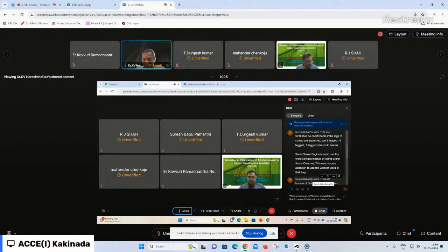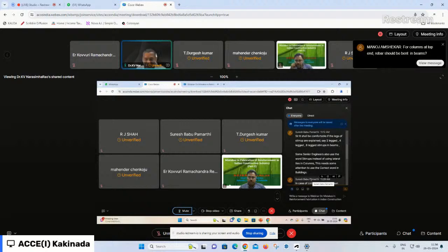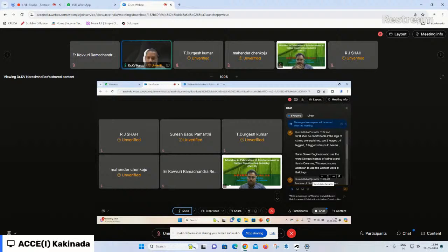That 8 bar can be fabricated as a straight bar for the main steel into the sunshade, and the same bar can be utilized in the form of stirrups by placing a stirrup anchor reinforcement. That is, it will have both functions: the stirrup in the lintel beam and also the main steel that is the sunshade top steel. That is the better way of arrangement.